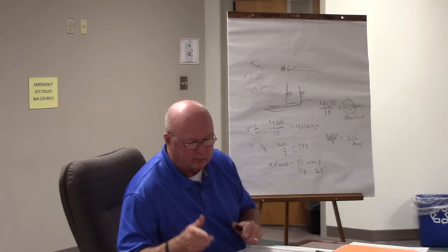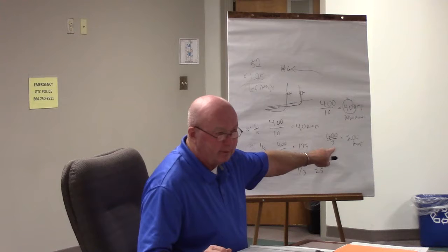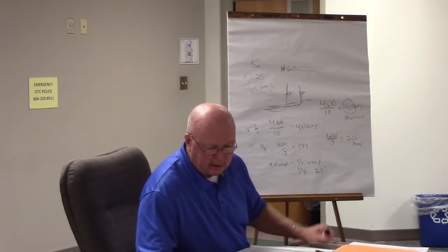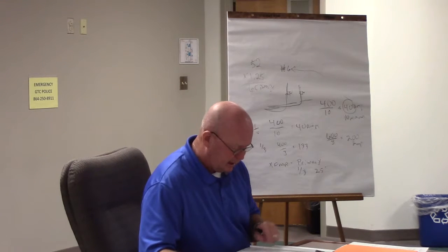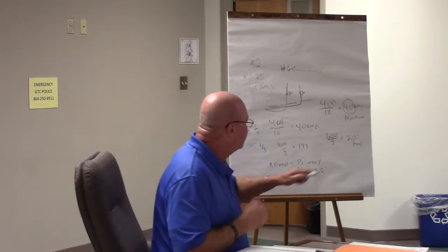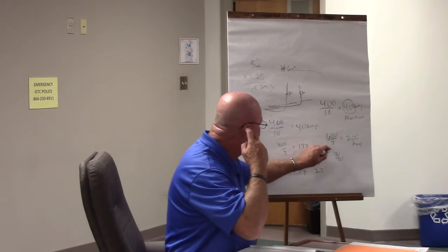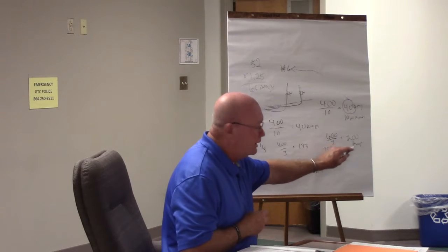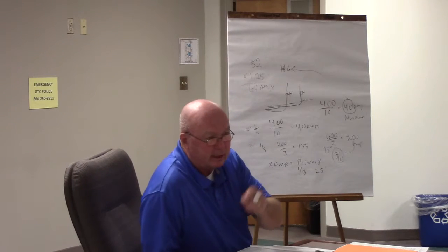So we've got to go to 310.15(B)(16). We've got to find a wire that's good for at least how many amps? 200. And we're going to go to what column? 75 column. And we're going to find that even though it's a 100 amp load, we have to use what size wire? 3/0. Okay. You understand why we did that? Because we can't use anything less than that, even though it says it's a 100 amp load.